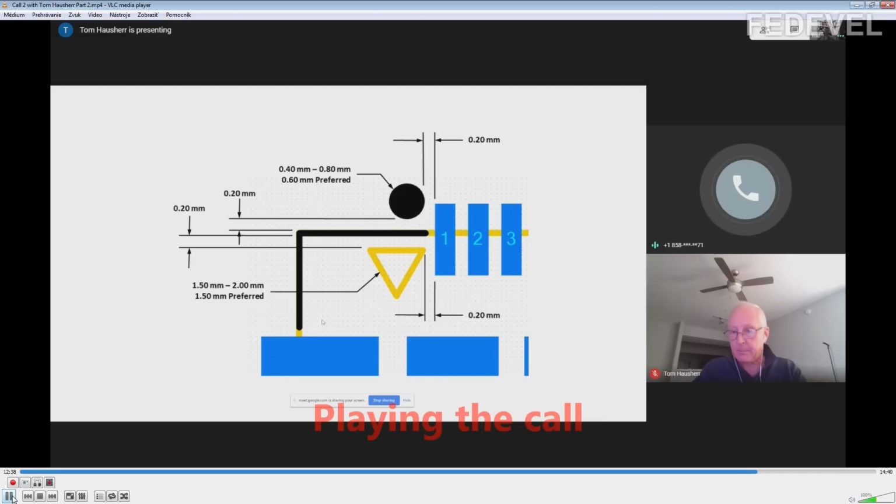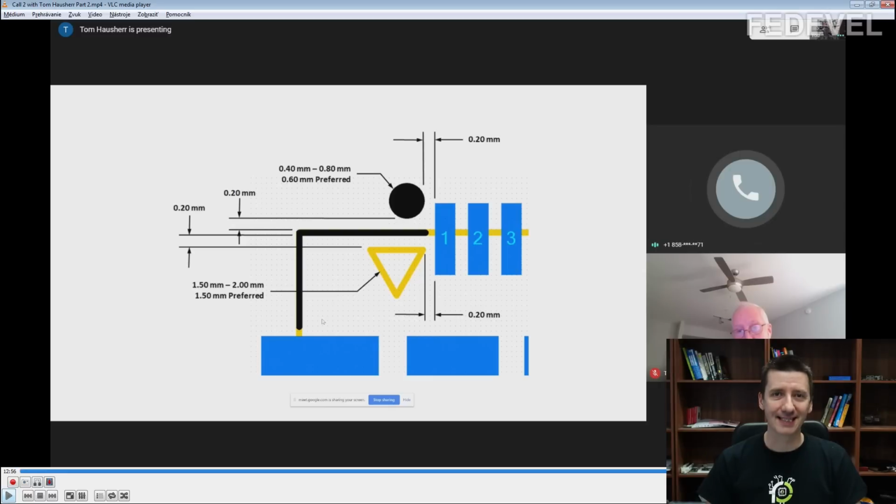And so when you get the assembled boards back from the shop, you look at your board and you look at all your legend dots to make sure that they're matched up with all the component dots. And if you see a legend dot on this side and the component dot on that side, way over there somewhere, then the part was inverted accidentally by the assembly. I know exactly what Tom is talking about, because I've seen so many boards with chips fitted the wrong way.